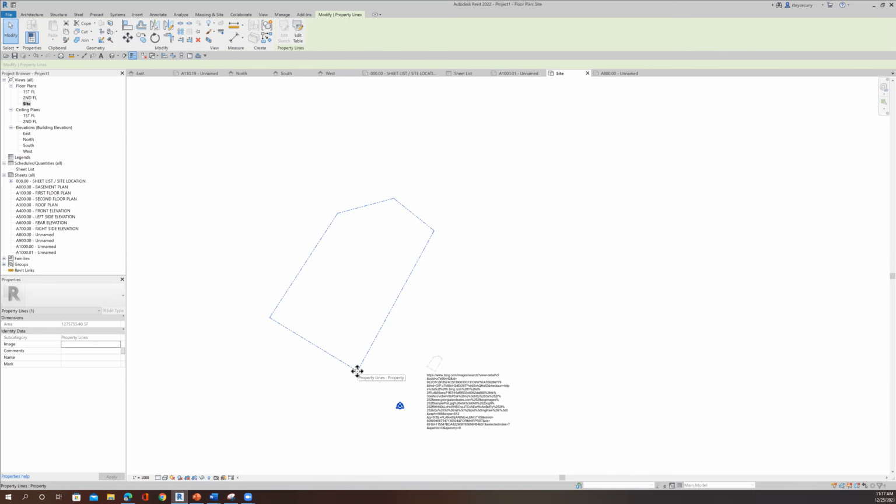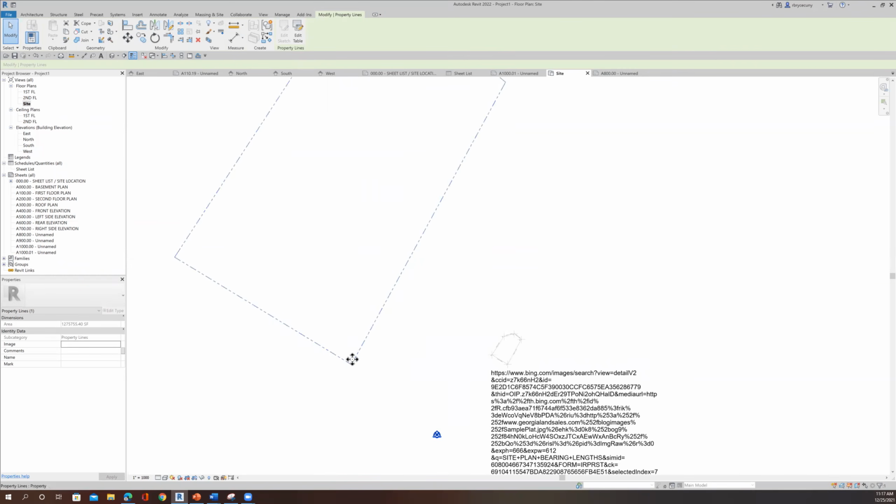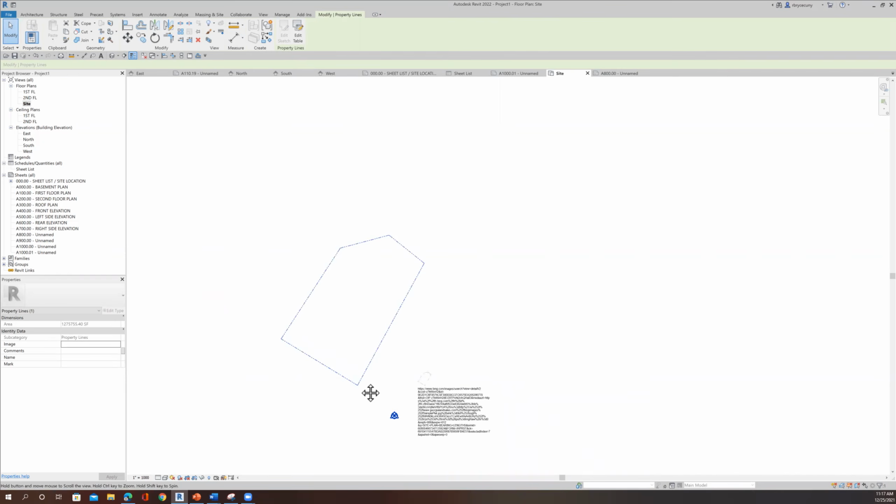So if ever I'm doing a site plan and it doesn't close, then it generally means that I have typed the distance wrong, but sometimes it could mean that the surveyor has put some information in wrong. That's very rare, but it happens. But anyway, I do not want to start until I make sure that it closes. The reason I want it to close is because this is a legal definition, and I want to make sure that I have created the correct legal definition, because the next thing that I'm going to do is create